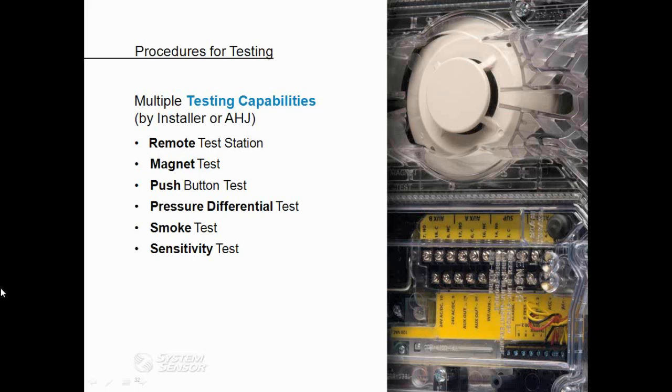One of the best ways, as we've mentioned many times already, for testing a duct smoke detector is through that differential pressure testing. This test verifies that the detector will properly respond to smoke by ensuring there is proper airflow across the sampling and exhaust tube. And this is done through the use of a manometer. The final way of testing is to apply smoke directly to the head.